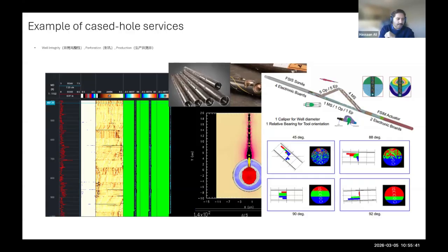So I can probably just give you a lot of these wireline tools. Wireline cables usually have an armor sheath, which is a combination of Kevlar and some other materials, especially very tough polymers. For the wireline tools, we use a lot of corrosion-resistant alloys, so stainless steels as well as Inconel or nickel-based steels.